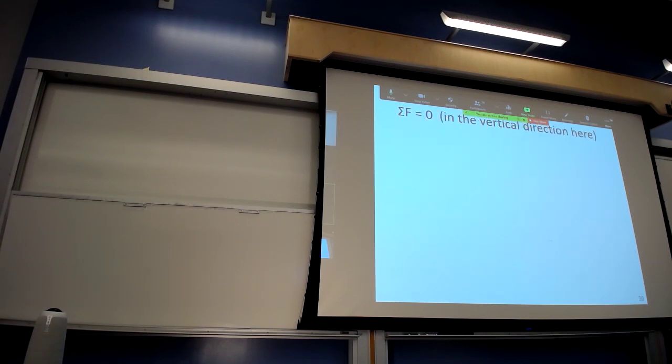We're going to look at Newton's first law in the vertical direction. So we're going to say that the sum of the forces in the z is 0. What are the forces? We have forces acting on the two edges in the y direction and the two edges in the z direction. But remember, because it's curved, those forces have a component in the xz and the yz. We're only looking at the components in the z direction. And so that's these forces. That's what's acting along the edges.